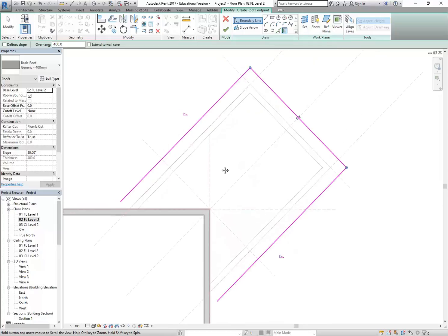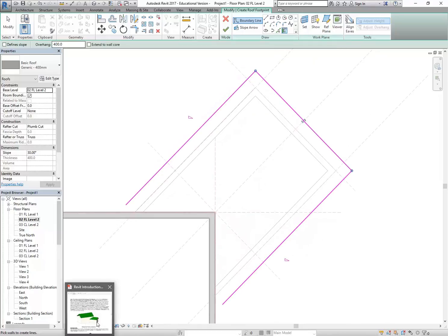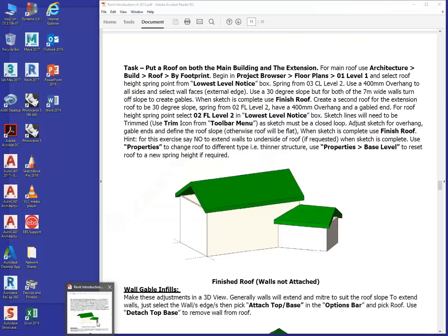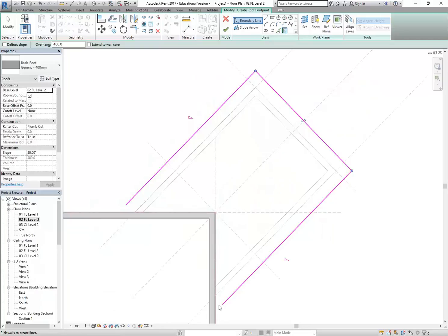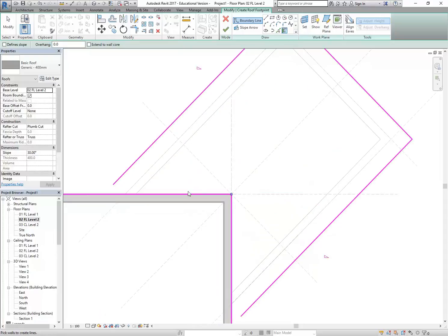But now you need to think about where the roof has to stop. So looking at the picture here, you can see the roof stops at the building, at the wall that we've got coming through here, these 2 walls actually. And so to get the roof to stop on that edge, we need to put the overhang back to 0. And that's the step people often miss. So you need to make the overhang there 0 before you pick this wall here, and then the other wall that's coming down at a right angle, so that the edges of your roof follow the edge of the wall exactly.